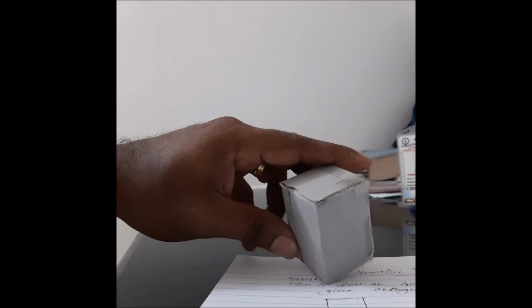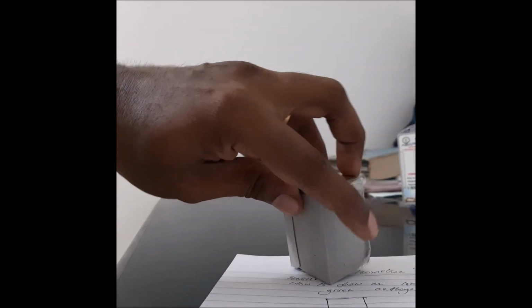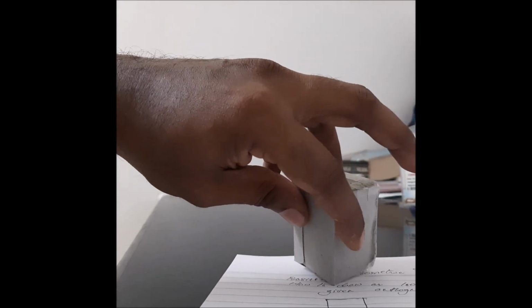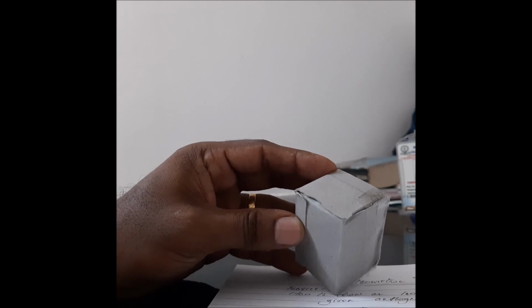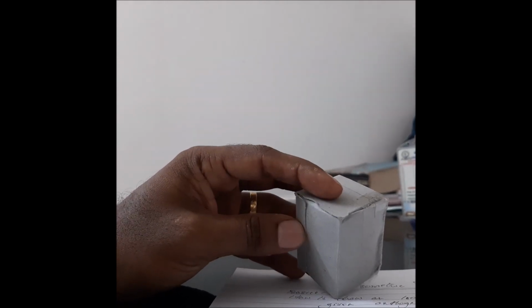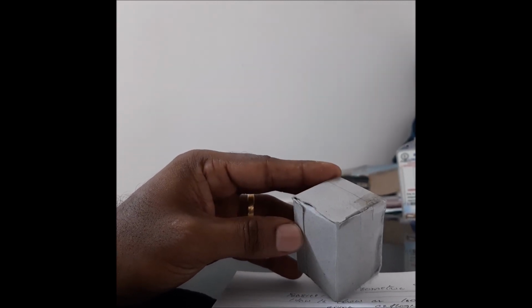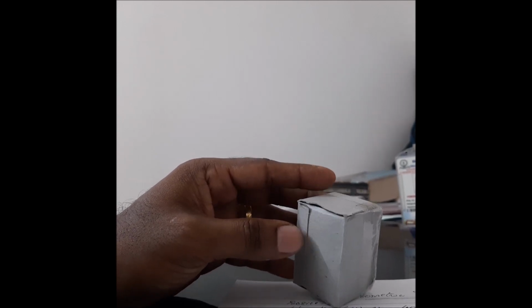Now what is the specialty of this? You can see at least three faces of the solid: the top face, the right face, and the left face. If you keep the solid in such a way that in the front view you can see the three faces of the solid, that gives you a 3D view. That is the essence of isometric projection. You rotate the solid to a position called isometric position. Now what is the isometric position? I'll tell you.